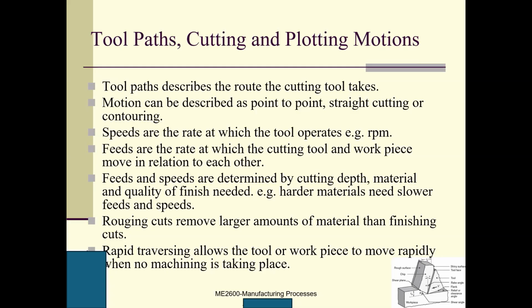The tool path describes the route the cutting tool takes. Motion can be described as point to point, next, straight cutting or contouring. And point to point moving is without machining, just from one point to another point.